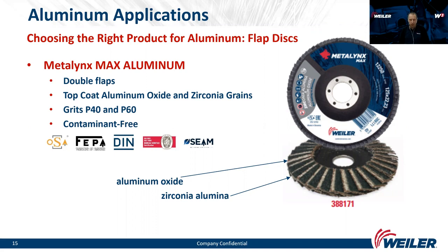Anyhow, as my colleague Franja and Doris already mentioned, we can use a flap disc for grinding and finishing aluminum surface. Some other very common applications for flap discs are edge blending, preparing surface for painting, or deburring machined or cut aluminum parts.